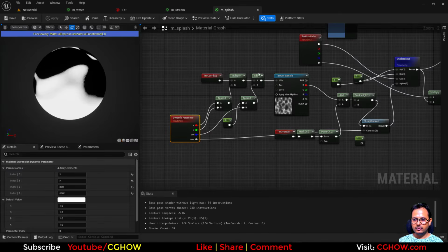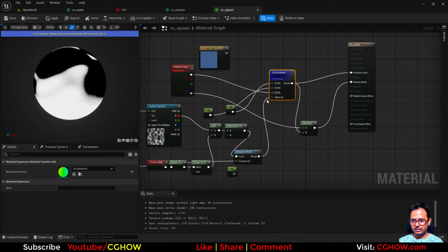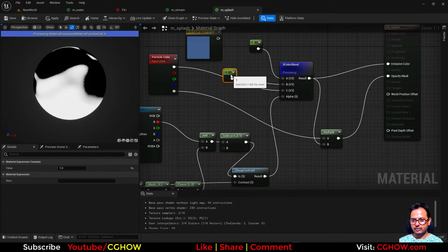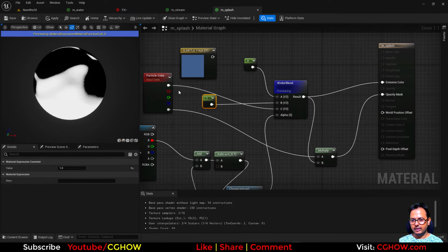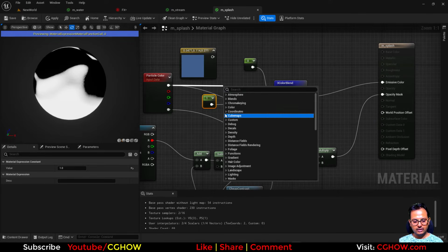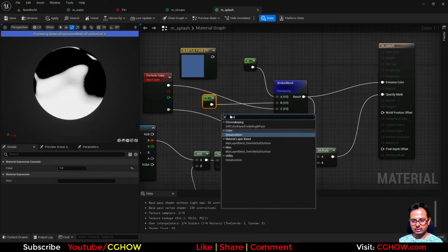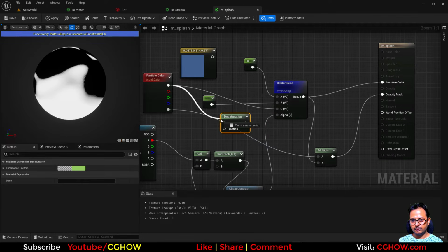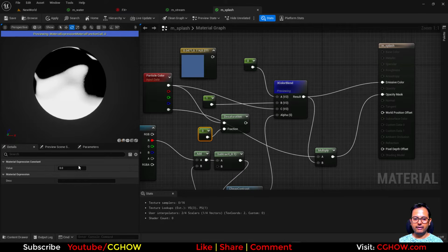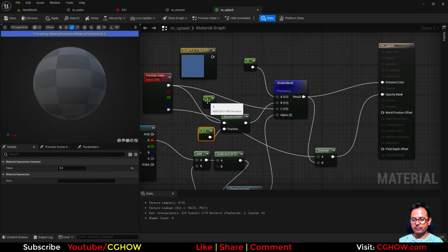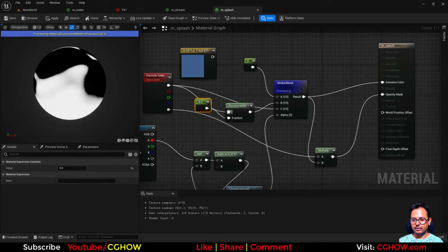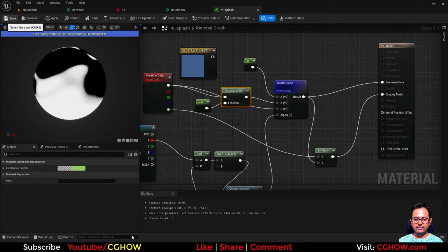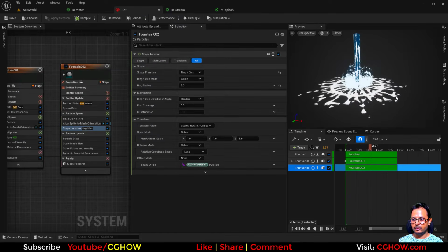And actually here we have this white here, and I will make this thing also particle color but slightly desaturated. So what I'll do, I'll take the desaturate and use the particle here, and let's say 0.5 value. So whatever I have in the particle color, it will take half of that saturation and put it here in the B. Let's save this again. Now check it here.